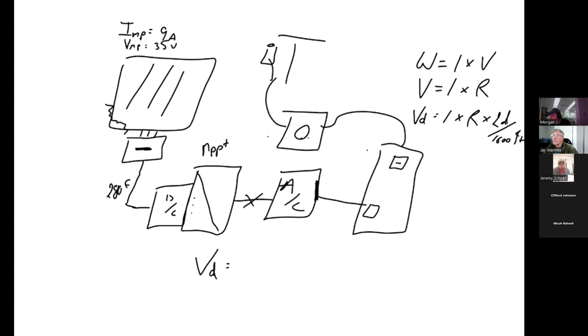It'd just be 9 times 3, right? 27 amps, because I've hooked 3 strings together in parallel. So when I do parallel, now it's going to be a 27 amp system, still 350 volts, because voltage didn't change. So I now know my amps, 27 amps.